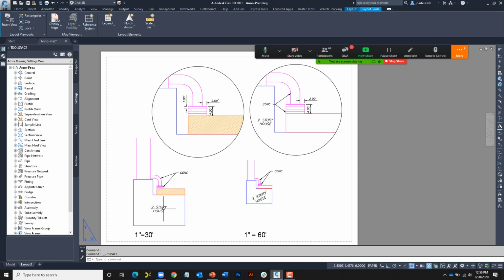Here I've got the same label appearing at the appropriate size in multiple viewports, independent location and rotation. Here I've got hatch that's displaying in multiple viewports at the appropriate size regardless of the scale. And then here I've got 2 viewports at the same scale, and I'm still able to use the annotative property to control their display. Do you want to build your empire on this? Maybe not. Maybe not, but I show it to you just so that you're aware of what the annotative objects are looking at. They're looking at the name and not the scale factor.